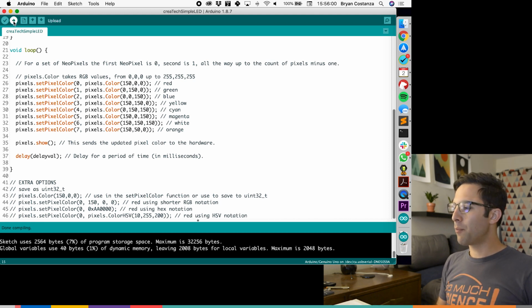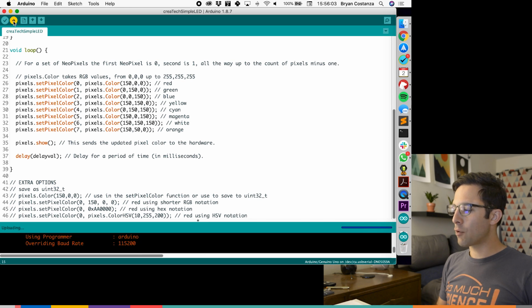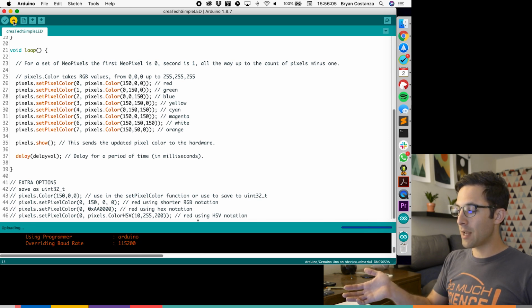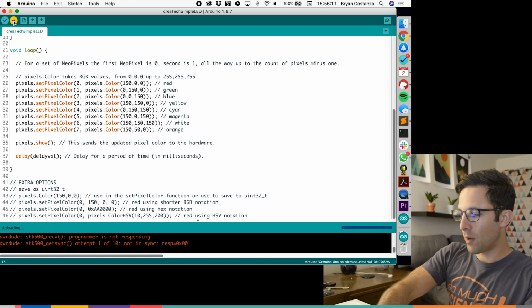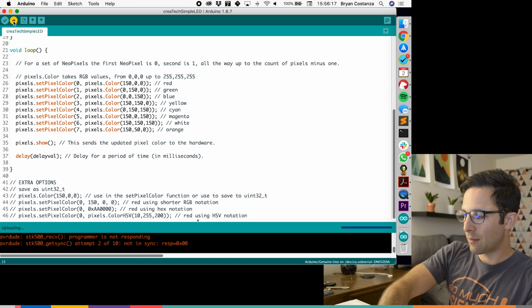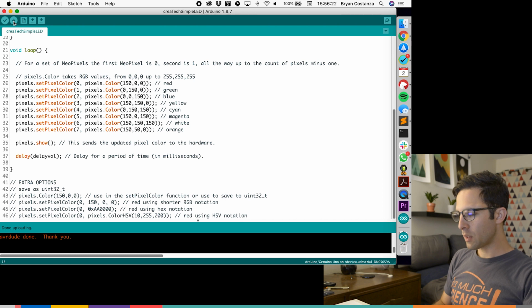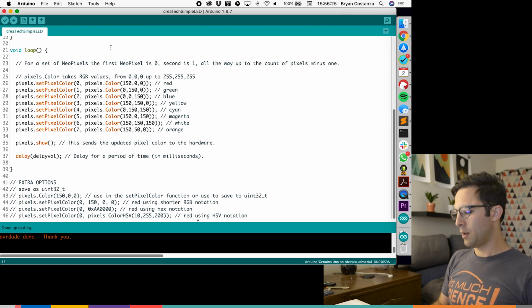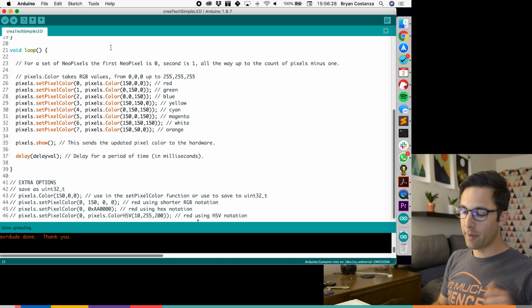And then right next to it is upload. So I can click that and it's now going to send the sketch that I created through the USB to the Arduino. Now my setup's a little bit funny, so I need to kind of trick it. If I can click it fast enough, it'll go. There we go. Now it's uploading. And the LEDs are still lit up because it's the same program that I was running before. There's also keyboard shortcuts. You can do Command U if you're on Mac, or look it up if you're on Windows.